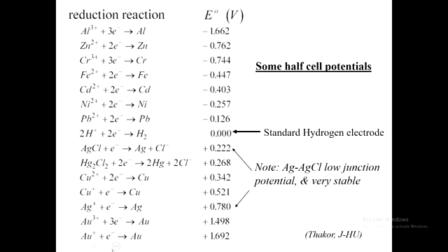So getting down to tin tacks, these are a bunch of electrode materials that are provided principally by Webster in his text. You can look it up there. Electrolyte pairs here, and once again the one of choice here is the silver chloride electrode. Quite a low potential that we achieve for that half cell.